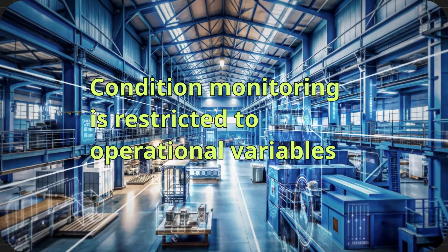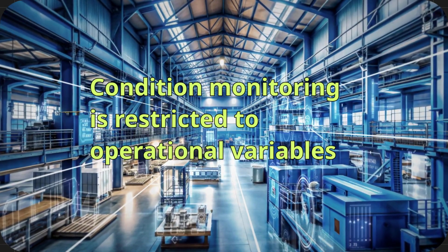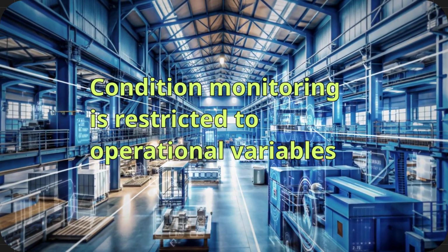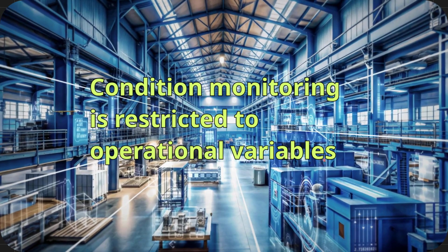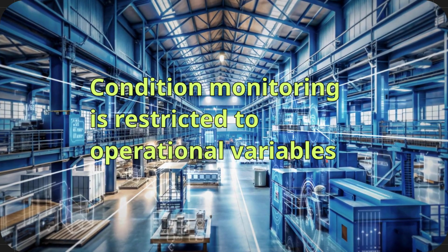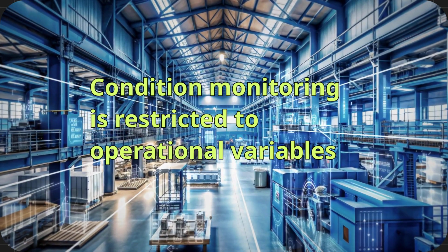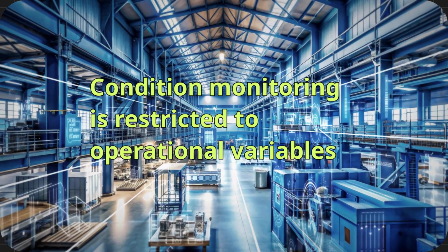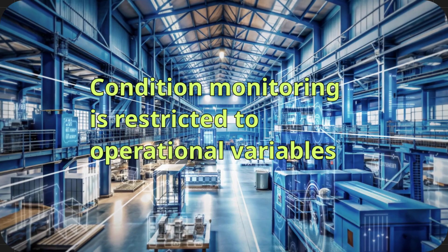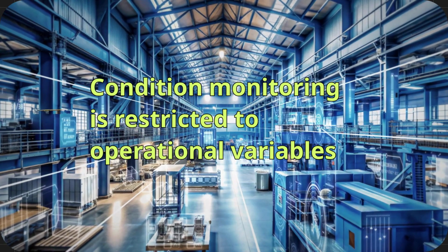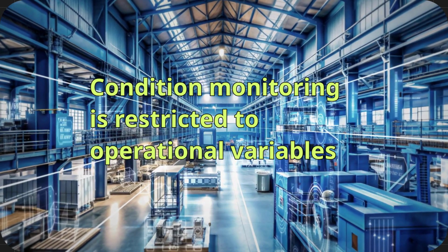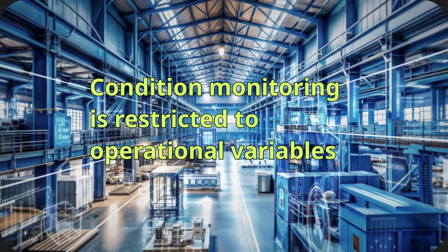Plant operators rely on information from various plant information systems to monitor the pump's operating conditions and identify any potential issues. However, despite the wealth of information provided, it can be challenging for operators to make clear judgments about possible pump malfunctions due to the numerous operating variables, such as varying tank levels, flow rates, pressure, LNG density, and pump operating hours. Additionally, given the pump's functional setup, condition monitoring is restricted to operational variables, meaning data such as vibration levels, bearing temperatures, and motor temperatures are not available.